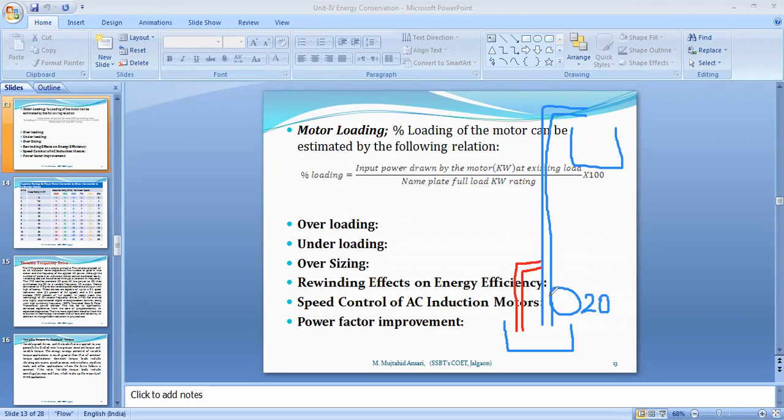So whatever water the 20 HP pump is pumping, the flow rate is very high. By opening the valve on this diverter pipe, some of the water is again put into the same tank, and we are able to control the output or discharge level. But this diverter is nothing but a loss in the system.